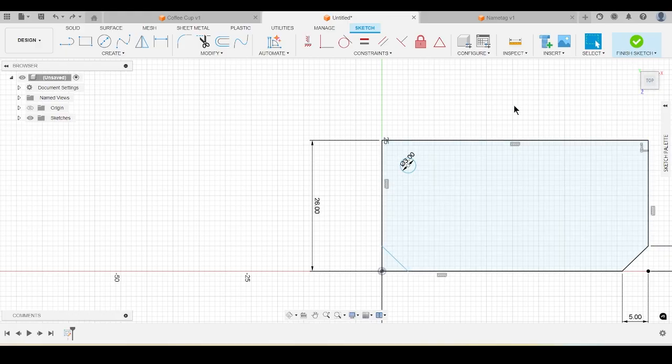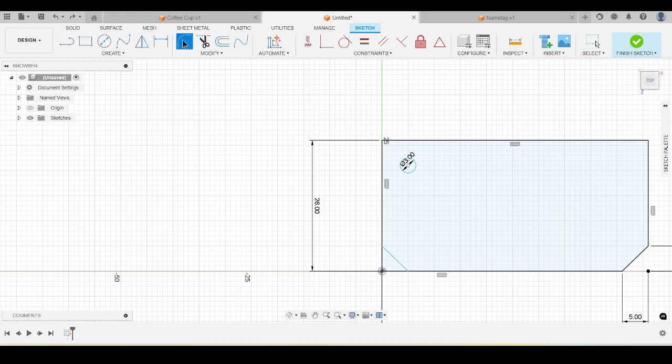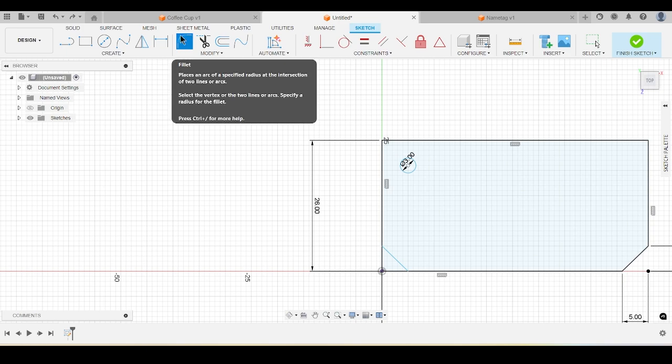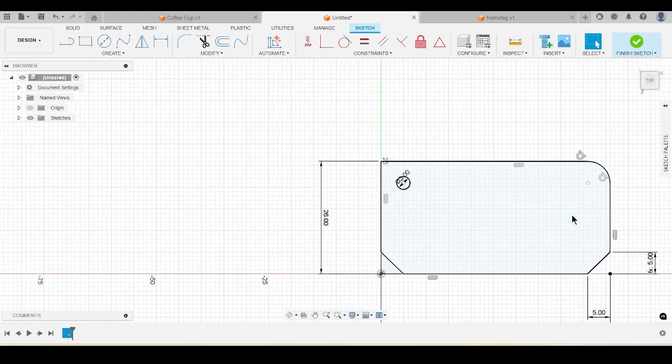And finally, this is the very last thing we're going to do for this video. So thank you so much, guys, for sticking around so long. We're going to just jump a fillet. So our fillet, as you can see by the image, is a nice rounded corner. We're going to trot a fillet onto this corner here. And again, we're going to keep it at 5 mil. We're just keeping it pretty uniform all the way around. All right. And just deleting that measurement there because I don't need it.